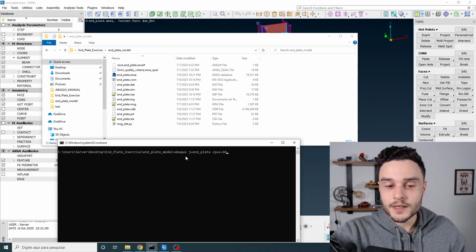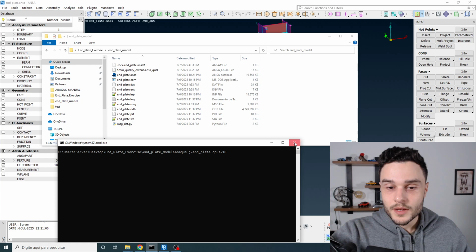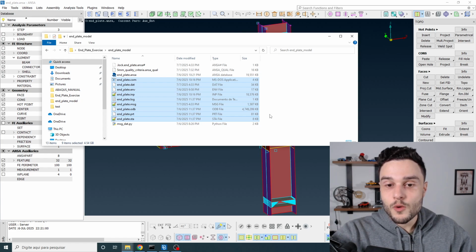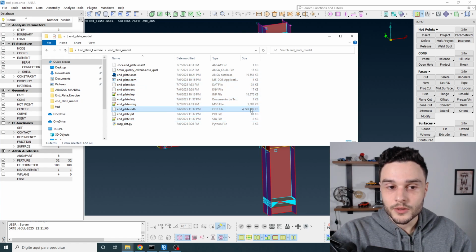When we press enter here, we end up submitting this job to Abaqus, and then Abaqus is going to solve this mathematical model using the finite element method. And we know that this solution is approximated. After doing that, Abaqus has generated all these files that you see here. In this video, we are going to post-process the results by using the .odb file.